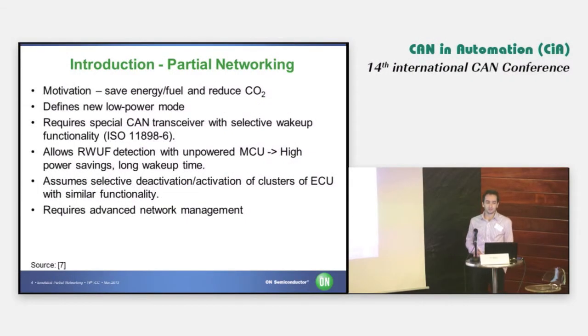Partial networking defines a new so-called low power mode with selected wake-up functionality. And a new requirement is a special CAN transceiver that is able to handle all the things defined in ISO 11898 part 6.